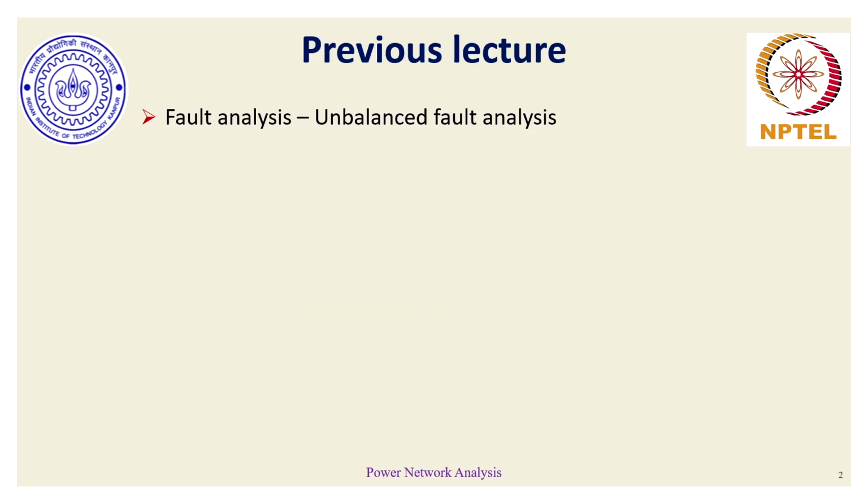So till the previous lecture, we had theoretically analyzed the application of Thevenin's theorem and Fortescue's theorem to evaluate the worst case fault current that can occur for asymmetric faults, which can be categorized as single line to ground fault, double L fault, and double line to ground fault.